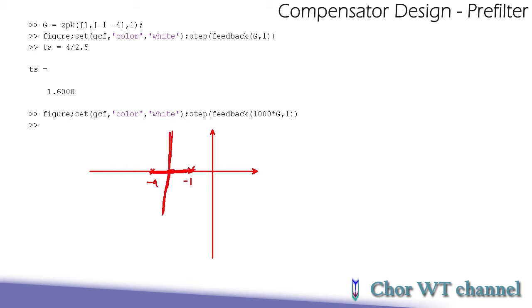whereby this will be the shape of the root locus. And then if I want to improve this, other than incrementing the gain to compensate for the low steady state performance, I also wish that if I can increase the gain, I will be able to make the system go faster. So for the system to go faster, basically I will need the root locus to bend towards the left hand side.